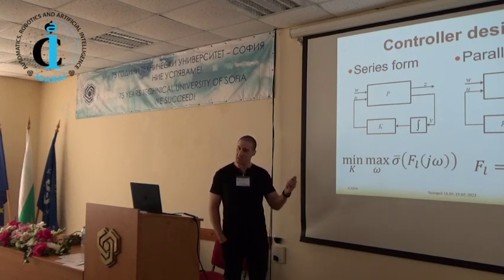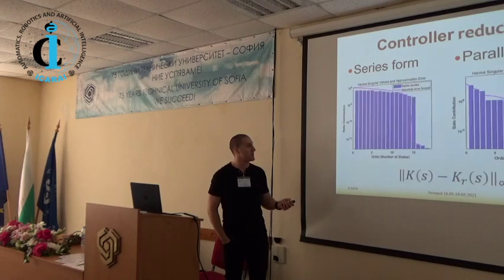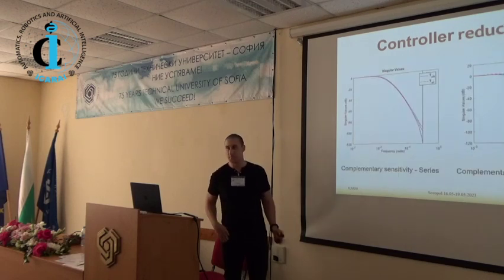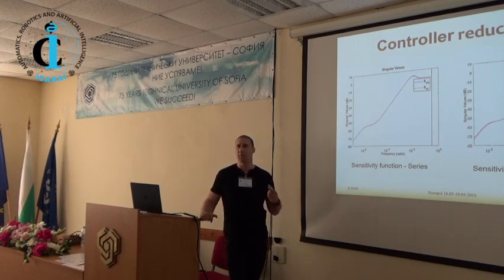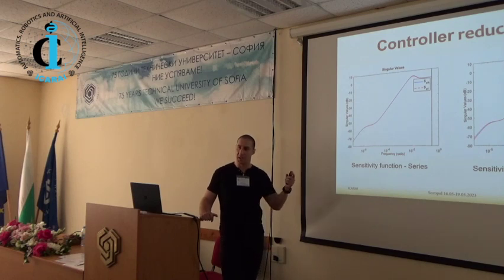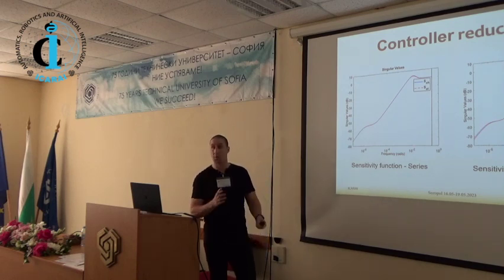The shaping filters are missing on the... Here, you mean? Is the thermal plant with delay or without delay? The model that we received from the identification procedure has one sample time delay, which is 10 seconds in our case. But for this dynamics, which is around 20,000 seconds in open loop, I would say that it's not big.